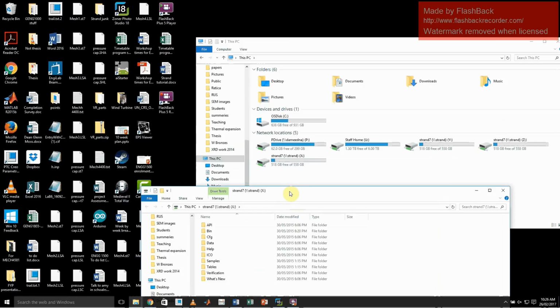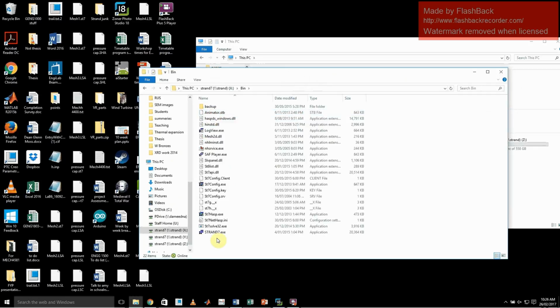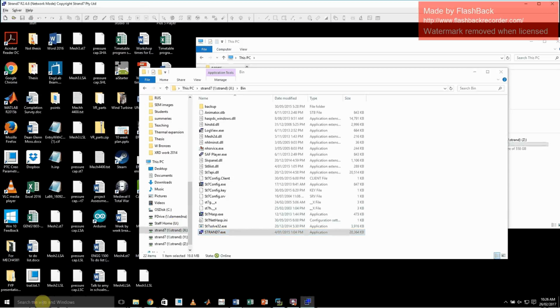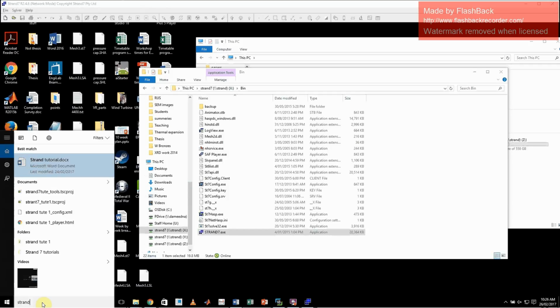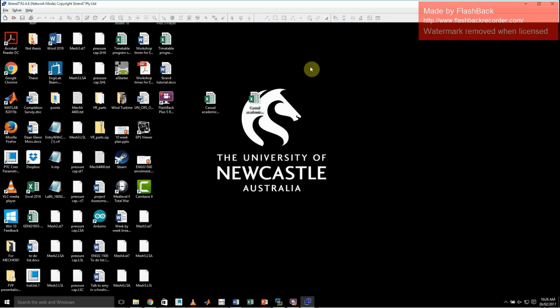Now, you might get asked for a few credentials and asked to log in, but that's all you have to do. Come down to your bin folder, go right down the bottom to the Strand 7 executable, and Strand 7 should start. As I said, most of you should hopefully be able to find it in here, but if you have any dramas, you can always just do this. Okay, so Strand 7 has started. It looks like this. It does not look like very much at all. There is nothing in it, but we've got the program running.